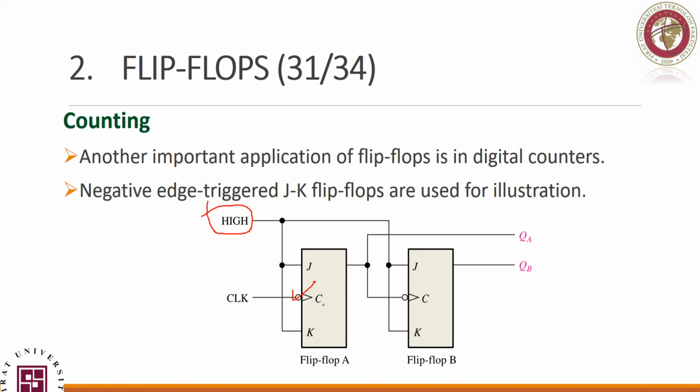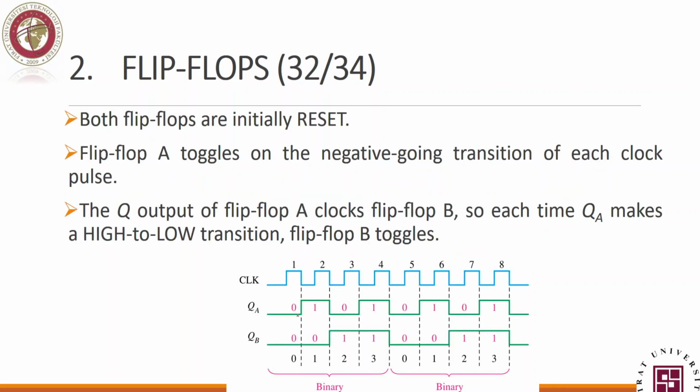Even 1 picosecond or less, maybe a fraction of a picosecond, it will take time. Until we get our output here, this one will not be triggered immediately. We have rising edge 1, and it will trigger at the falling edge. When will the falling edge happen? The next clock falling edge.